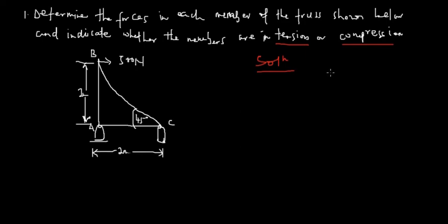Okay, right. So let's look at the free body diagram for each of the sections. Let's start from maybe section B. That's where we have our force, so it's better to start from that section. When you are drawing the free body diagram for section B, this is how it will look. We have this force going downwards, and then we have our 500 newtons.